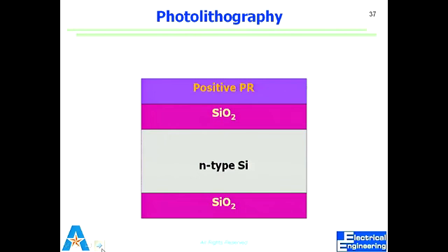Coating is, we use that chuck to hold on to the wafer. We rotate it at 4,000 RPM and we apply a liquid in the center of the wafer. First we put the liquid in the center of the wafer and then we spin it. Think about it. What will happen to the liquid? It will fly off. While it flies off, it's going to result in a thin uniform layer on the surface.